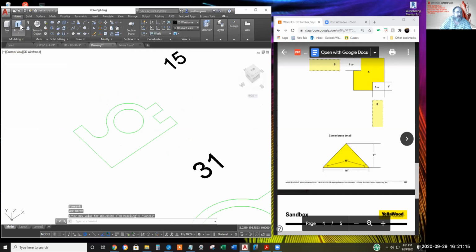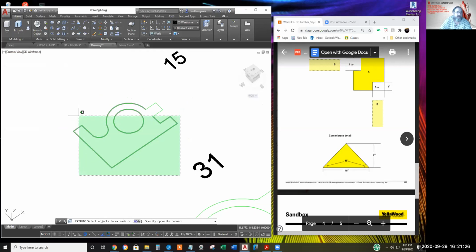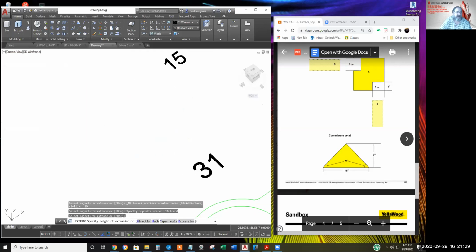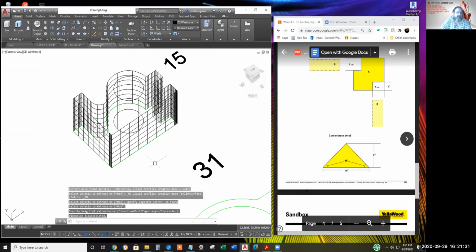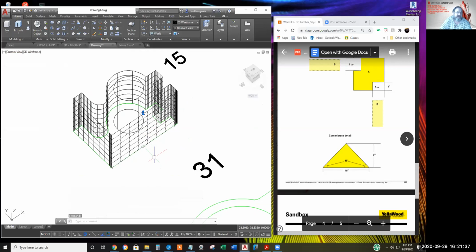And let me show you, again, a couple students turned it in without P-edit joining all these lines and arcs for the perimeter. And lo and behold, you end up getting this cattle fence looking surface model. Each one of these is a surface, which is great for making Hollywood movies, but they're pretty useless to go further into engineering work. Let me undo that.